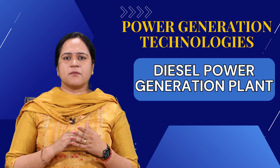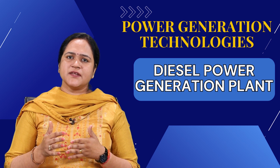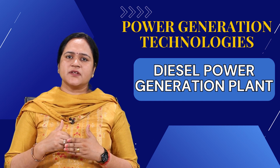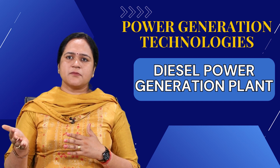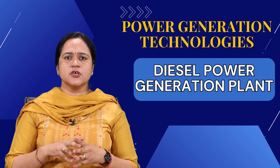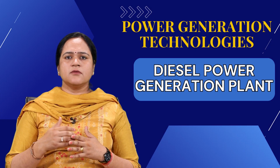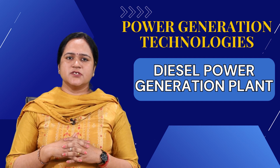Why? Because in a diesel power plant we only take the engine, and from the engine we get mechanical energy, which is converted directly into electrical energy. But in a steam power plant, first steam is generated, then the steam moves the turbine, then it is condensed, and then it is converted into electricity. So there are more components, and at every step there will be some losses in mechanical or electrical power. The losses will be more at each and every step and hence the efficiency will be down.